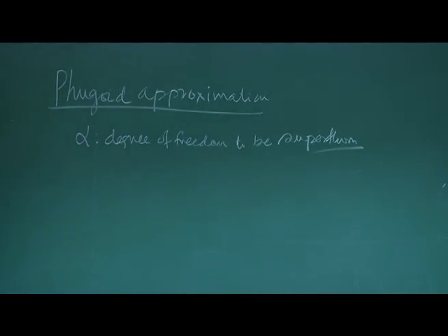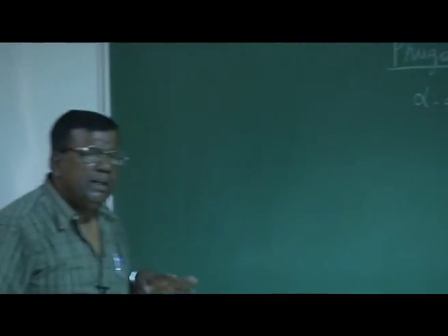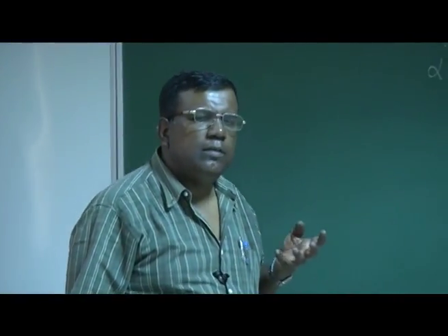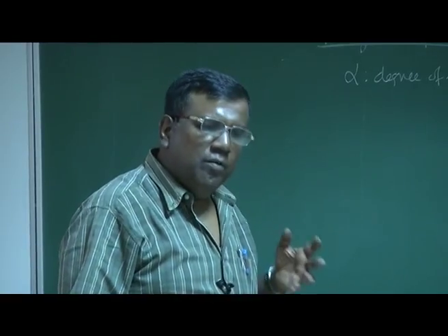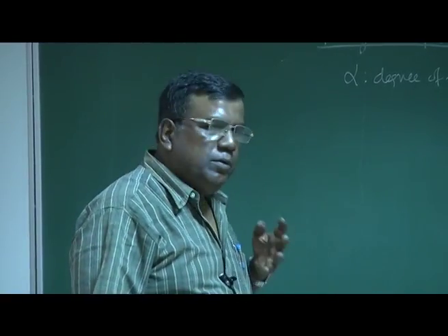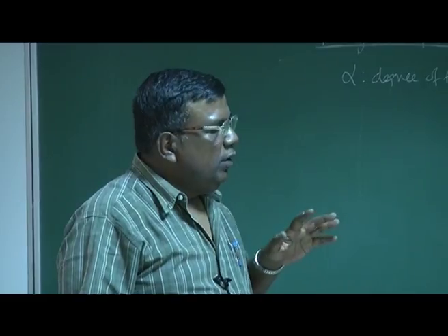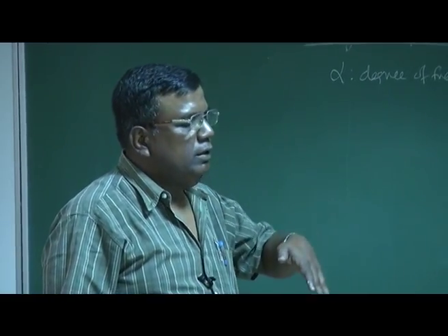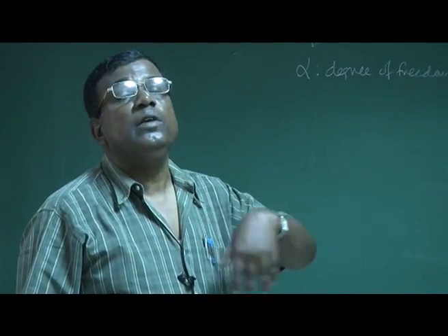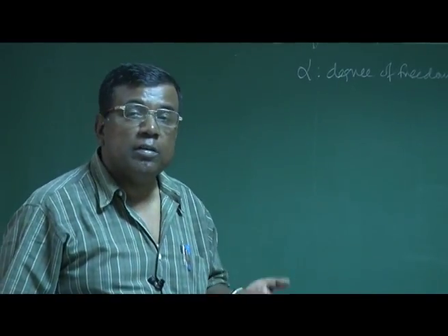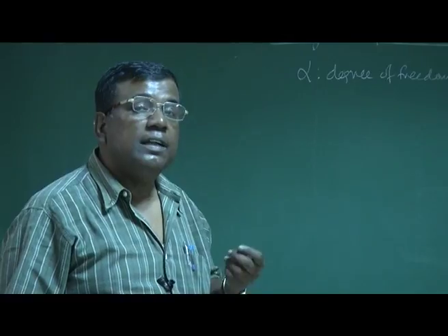We are saying that during the Phugoid mode, the approximation is not very correct, but it is not that bad either. It's not the worst approximation. It's not a very good approximation, but it gives you some feel. So in the Phugoid, it's assumed that the angle of attack perturbation remains the same. So the angular perturbation, or the angle of attack, is neglected.